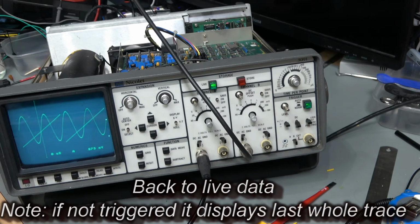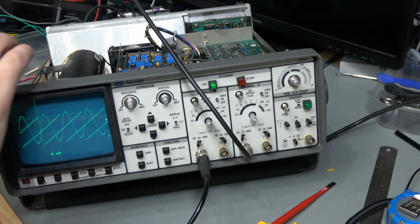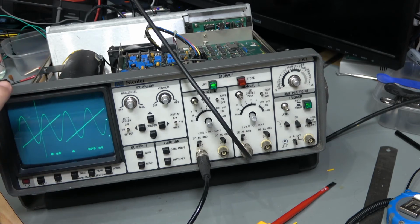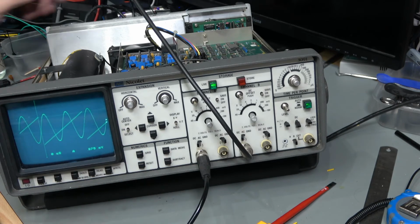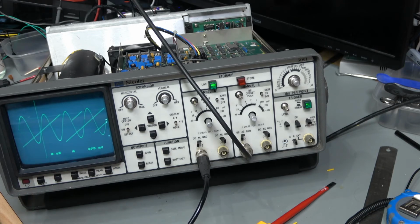Well, I think it's time to put all the knobs back on. Now I do need to take a little look at the power supply again, because I'm getting a couple of false starts here where it kind of starts up and then fails, and I suspect that there's a current setting on the power supply, and what's happening is we're getting too much like a surge current through, and that's triggering the power supply to shut down. I suspect that's what's happening, don't know for certain. It'd be nice as well if the on-off light would illuminate, but that's probably a neon. I'll see if I've got one.